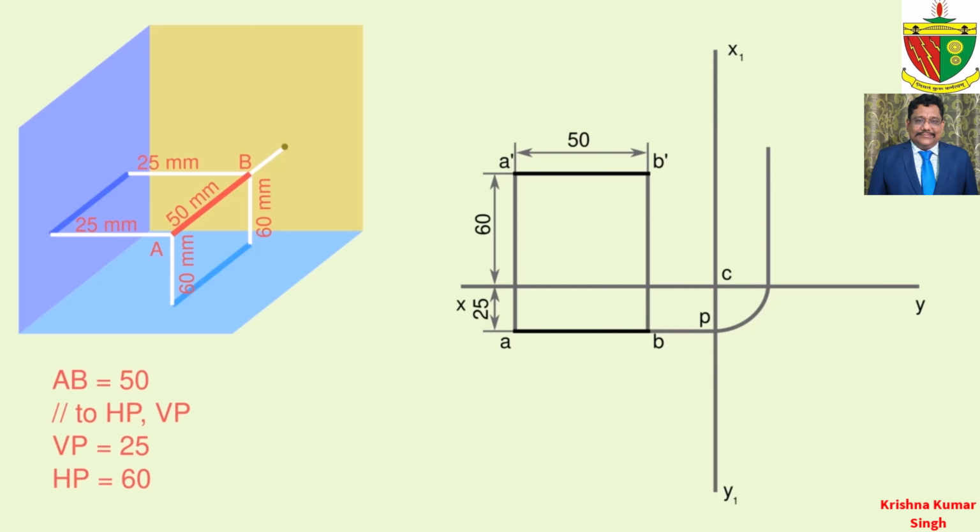From there, draw a vertical line upwards and extend the line from the front view to the right side. These will intersect at a point, which is our required side view. And then name this point with lowercase letters with double dashes, A double dash and B double dash.